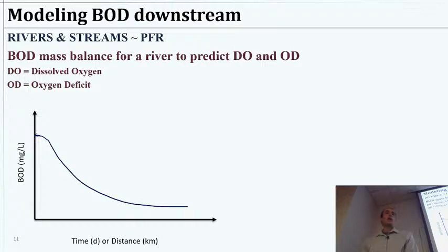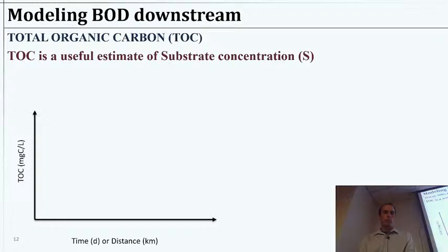There's probably some natural BOD in the water, just from fish, wildlife, soil, organics discharged into the water, all of that. There's probably some innate biological oxygen demand. And so we're going to approach that, the natural level, over time. Now, if we then consider what happens to our dissolved oxygen over time, we'll come to that.